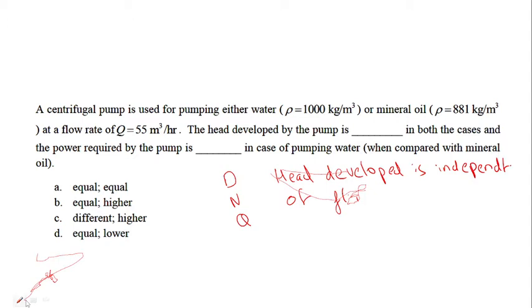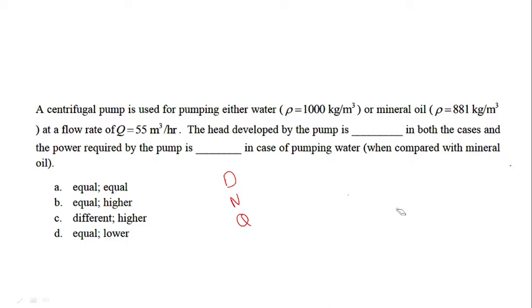A similar question was asked in last year's exam, on how the head is varying. But the head developed is independent of the fluid, therefore for water and mineral oil the head developed is the same.